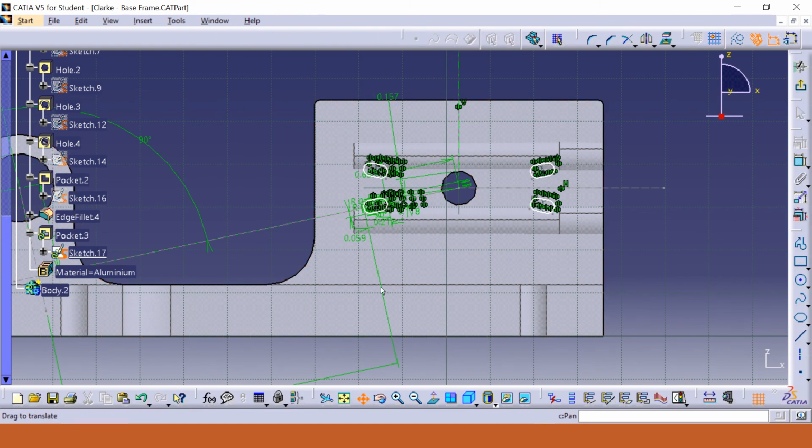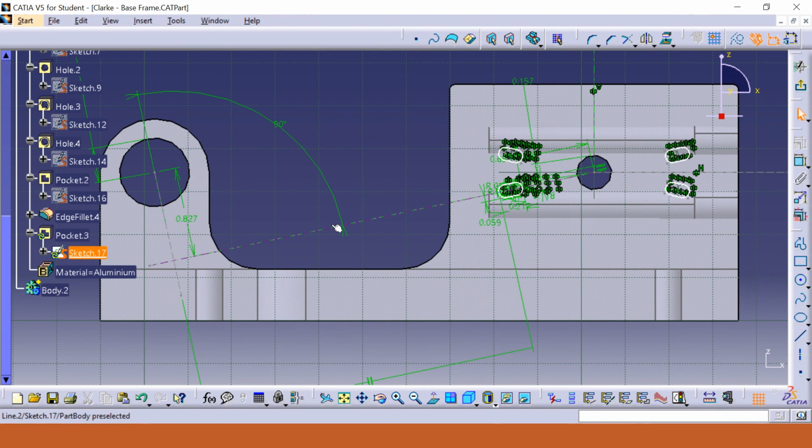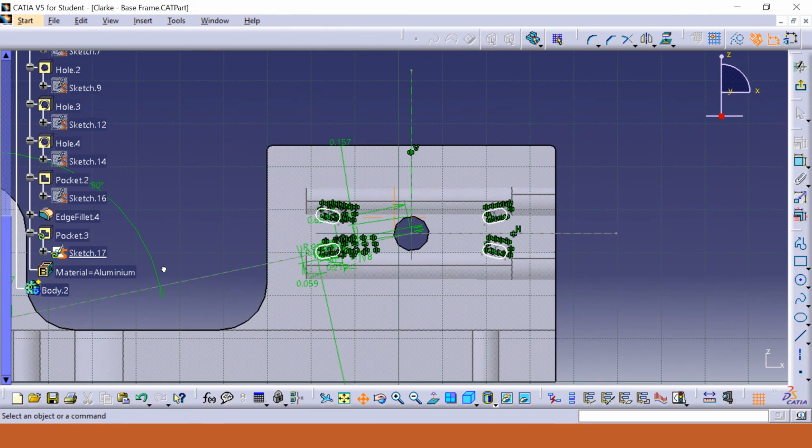by a construction line. Now, the construction line, which is this portion right here, was constrained to 90 degrees to a second construction line from the origin of this hole right here. Now, these lines were made this way as shown in the drawing designs from the start of the project. Once the construction lines were made, this rectangular portion with fillets on the edge was created along one, and then a symmetry tool was used to mirror first this one on this side, and then mirror both of these on the top.